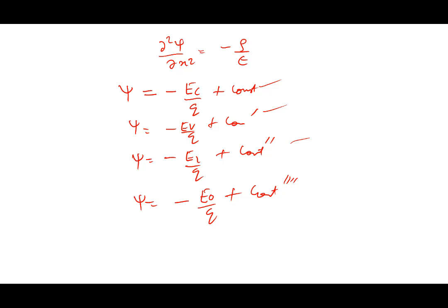So if you look at that, in equilibrium the only equation I need to solve in order to understand what is happening is Poisson's equation, right? Which basically boils down to finding out how potential and electric field vary inside the device. And with this relationship between potential and all that, it basically ends up finding the band diagram.